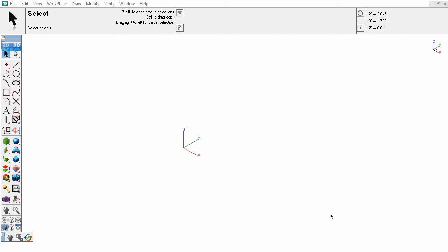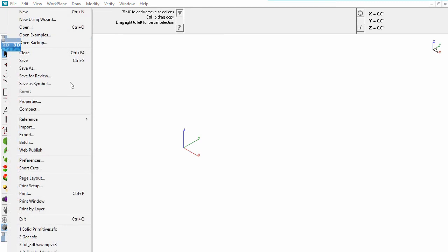When a surface object of multiple components is imported into the editor, the Mesh Analysis tool can be used to separate the components into their constituent parts. In this example, an STL file will be imported into the editor.